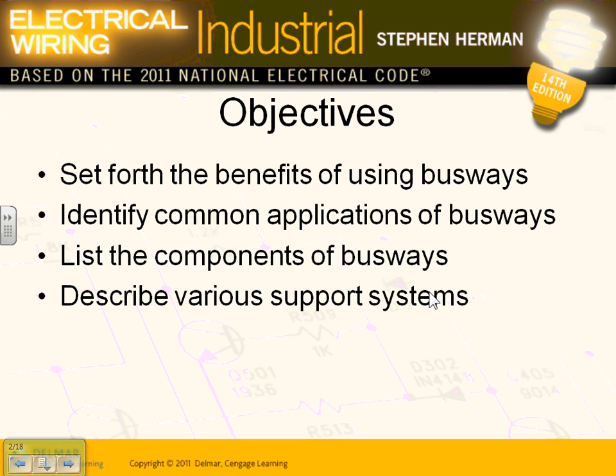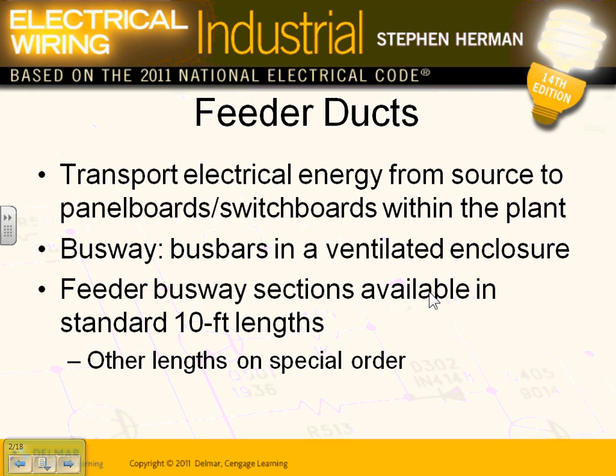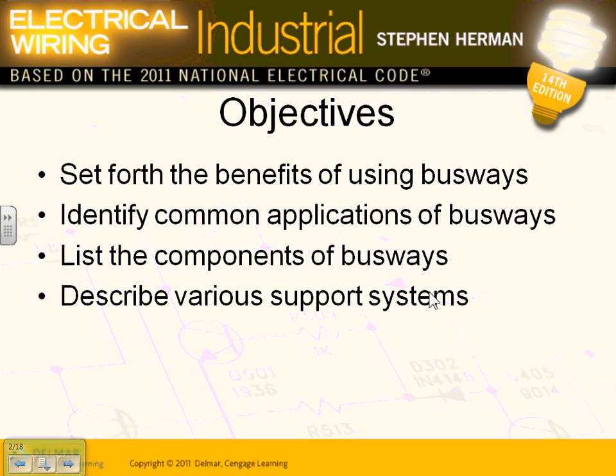Components of busways, we'll talk about in a second. The busways are made out of sections and connections, where you have to connect every 10-foot section. You have a box to connect these sections together. If you need to tap out of a feeder busway, they call it a tap box. If it's a plug-in busway, you have a plug that you can plug into and tap out of the busway.